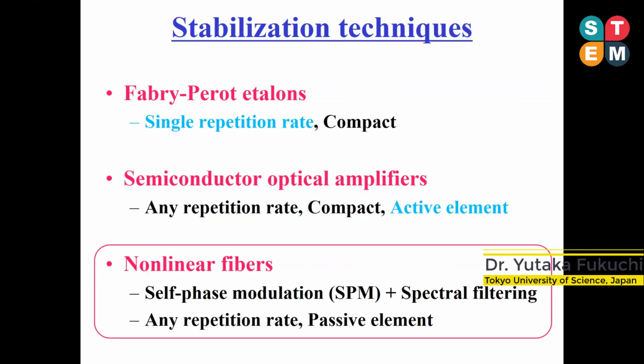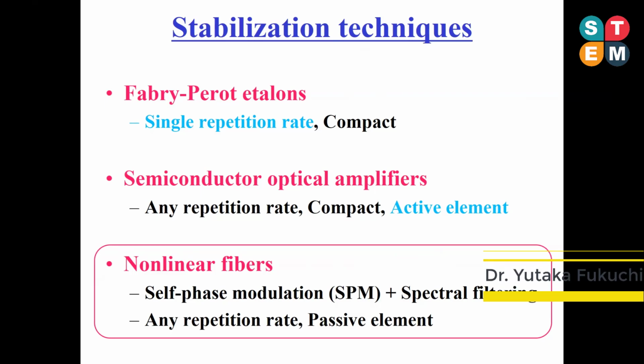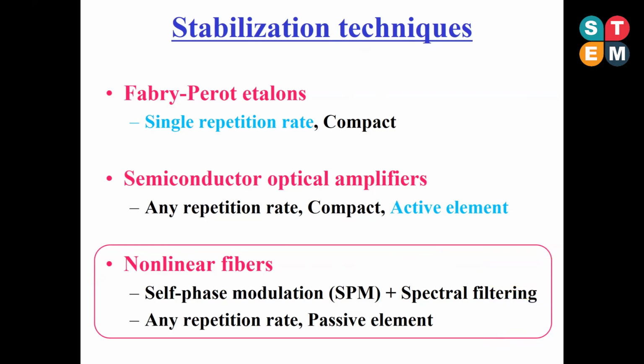In this scheme, higher intensity pulses are spectrally broadened by the self-phase modulation and then suffer higher loss through the optical bandpass filter. Therefore, fast intensity limiting is achieved and the pulse intensities can be stabilized.